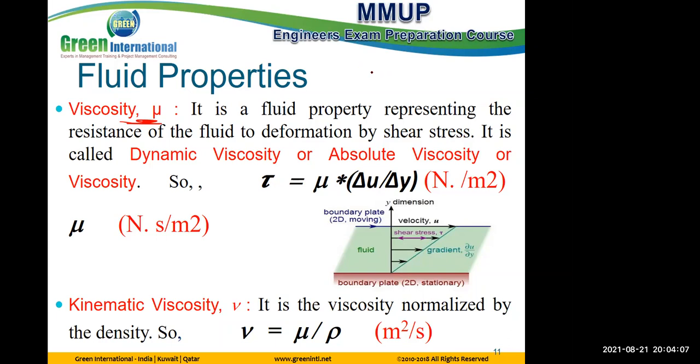So the flow is moving like this. Due to the flow moving, the layers shift relative to each other. The lower layer is in contact with the stationary plate, for example, so for sure there is more resistance with the fixed one, and its velocity is almost zero.